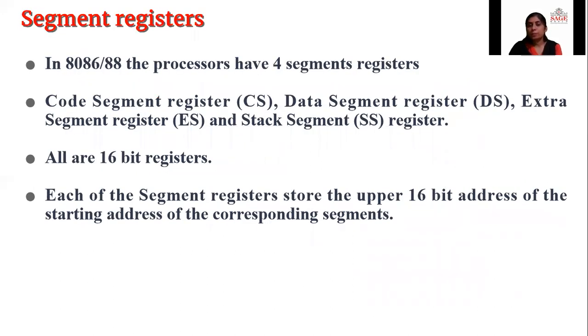Segment registers: 4 segment registers are there: code segment register, data segment register, extra segment register, and stack segment register. All are 16-bit registers, and each of the segment registers stores the upper 16 bits of the starting address of the corresponding segment.